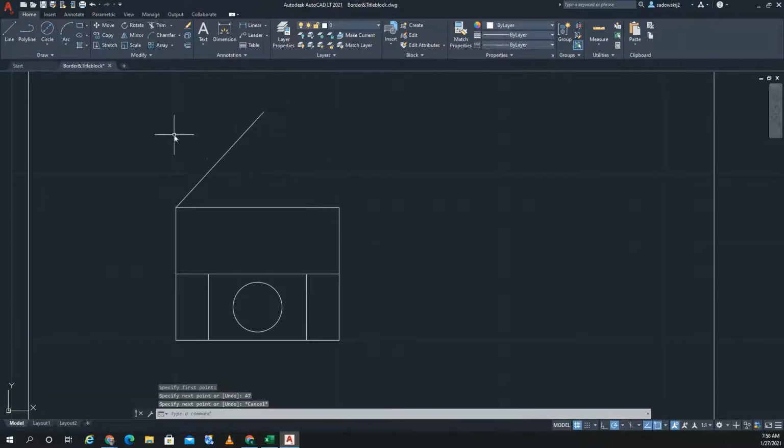Okay. Another one over here. Now I can't put 47 in because 47 is over here, because 0 is here, 90 is here, 180 is over here. So when I stretch it over here, what I have to do is 180, subtracting the 47 from it. So I go over to my angle at 133. Okay, just like that. Now I can also offset that one, yeah, 0.5 would be good. Up there.